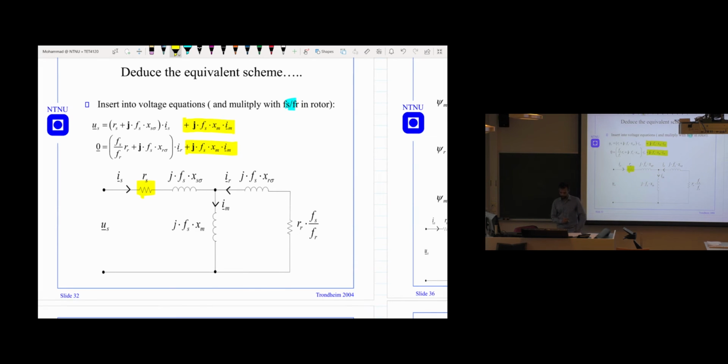So we got two very nice equations, and one thing is common there, this part. We see that this part is common, and here it is multiplied with this magnetizing current, or the mutual current. So now we can easily draw the circuit. It's in a steady state condition, and also they are in rotating coordinates. This means all the variables here are DC quantities, not anymore sinusoidal quantities.